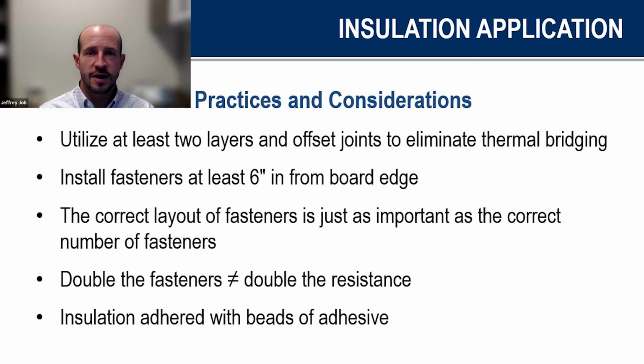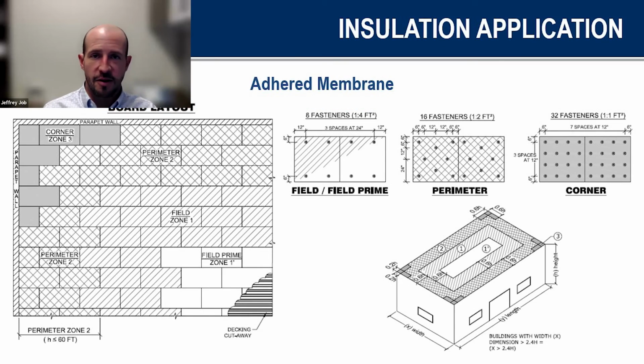The additional cost of a coverboard can be offset by cost savings in some of the other components, potentially less adhesive. If it's a CGF board, fewer fasteners in a lot of cases. A lot of manufacturers have varying capabilities around how many fasteners they allow per some of the uplift requirements. At least with JM, we can get an FM 190 with 8 fasteners per board with our standard HD ISO coverboard. Some of the other manufacturers have similar, some have higher. It just depends on what testing they've gone through. So that's another huge one there.